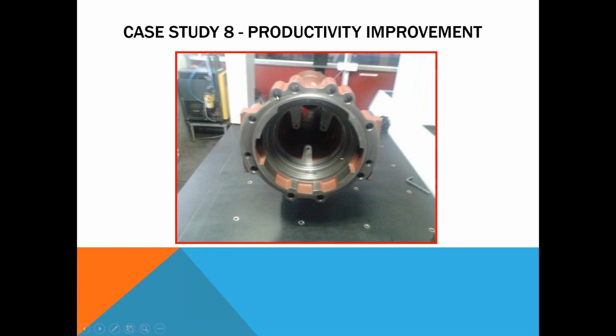Here on the face there is a rough milling. Here there is a milling. This was milling, and these are the boring. And here there is a chamfer. You can see this chamfer, this chamfer, this chamfer. And here there is a small 6 dia hole drilling.